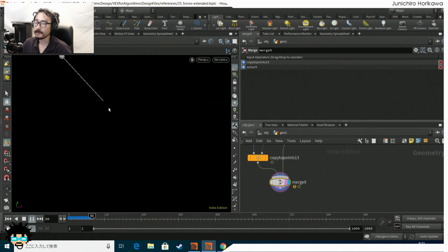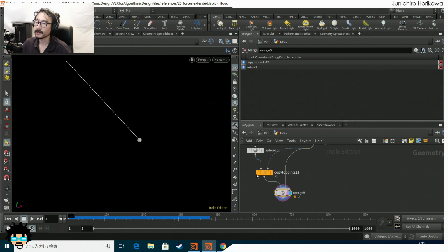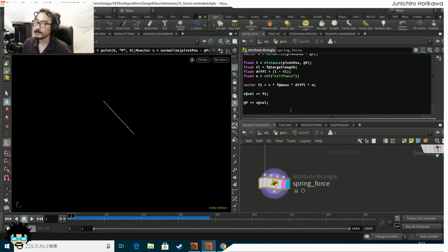now you can see that it's going back and forth in a single direction. I think it is actually working. There is no damping, so it's not slowing down at all. So you might have to create some damping value as well, so that at some point it will just stop at the length that I want. Let's try to do that.